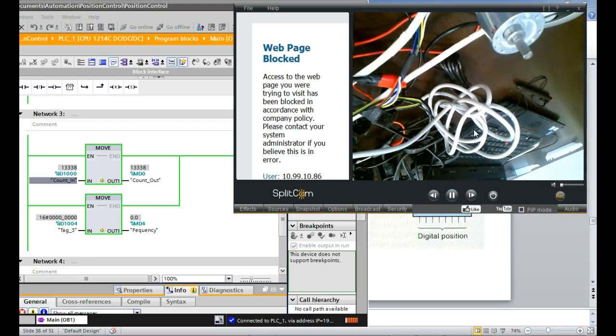And then I'm going to reset this thing. So that's switch 4. Okay, so I want to make it go 1 revolution and come back to this exact same spot. What count would I be looking for? We're going to spin it in the clockwise direction, and I want to stop it right here at the same spot it stopped at now, pointing right at the camera.